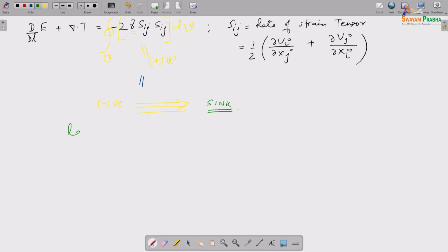So, when we had larger eddies, we looked at the length scales at which this was happening, right? We looked at the Kolmogorov length scales when this was happening. We wrote that down, and this was happening over a range, right?